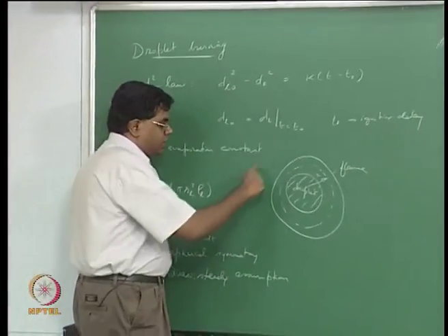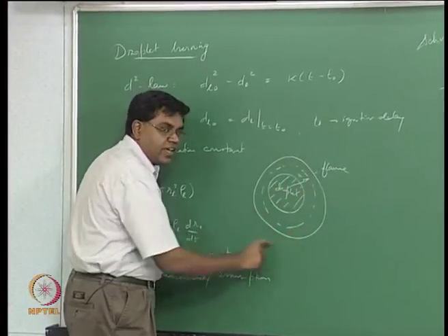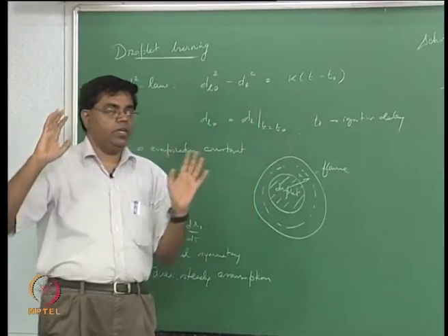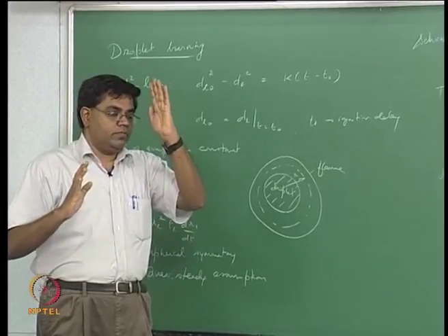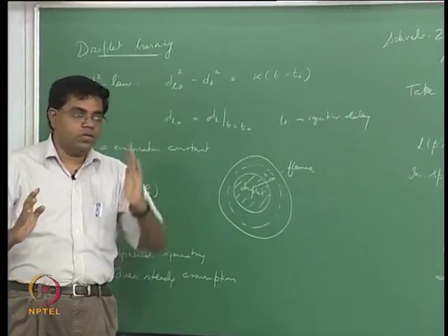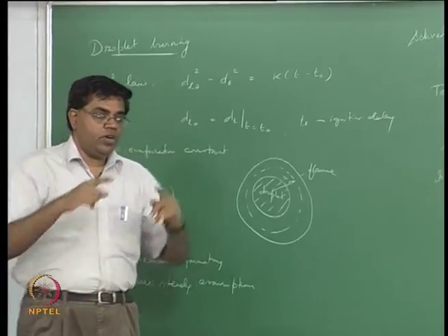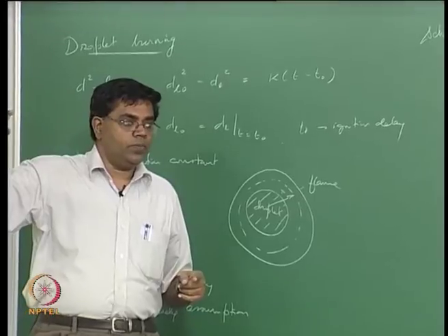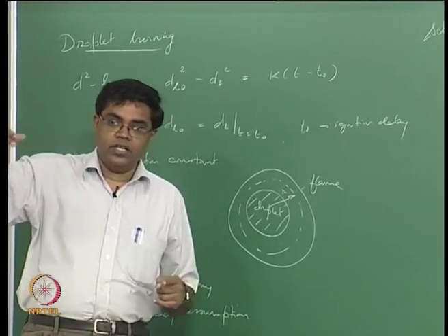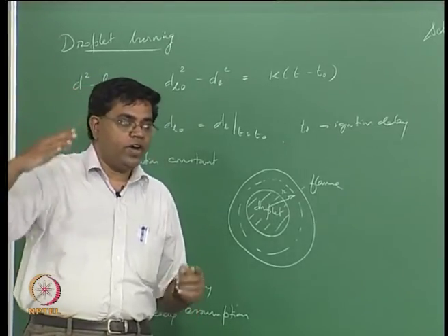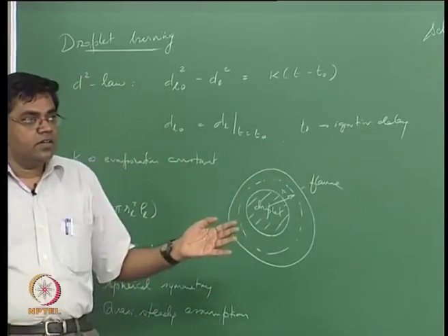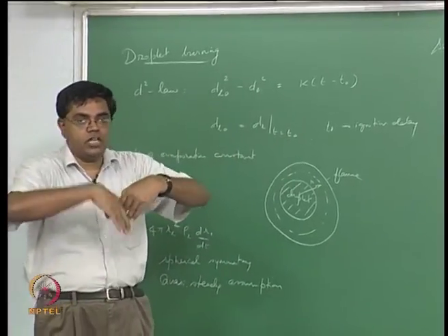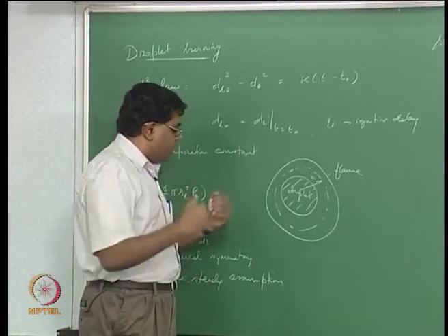You're going to have the products being formed at the flame, right, and just like how we thought about the flame as a flame sheet in the Burke-Schumann problem, we tried to locate how the temperature profile and the product concentration profile would vary away from the flame on either side, and of course the fuel concentration and oxidizer concentration plunging in at the flame and so on.